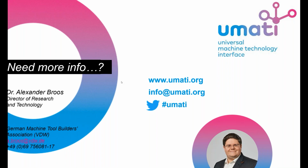So when you know which signals you want to have and you have an old machine, I think there are various ways you can imagine. If the old machine already has a digital interface, you can see if you can program a connector that taps into this old interface. Certainly, it cannot provide you all the data that is foreseen in the specification, but sometimes it's just enough to get a very limited set of data to already reap a benefit of knowing the status of your machine.